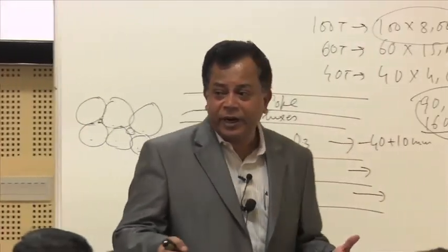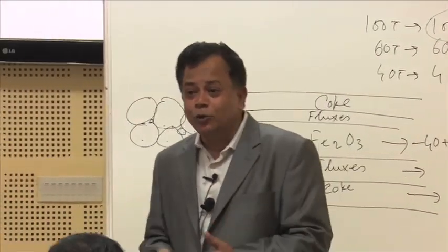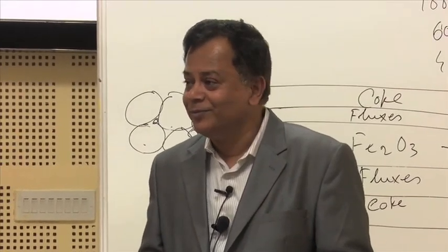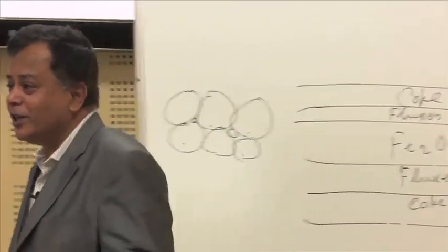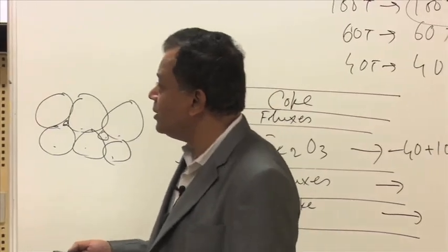Even if your mined coal gives you proper liberation, for the separation do you have equipment? Suppose I have to process coal of 1 meter size in my equipment, whether my existing equipment can handle a feed size of 1 meter, that also I have to look at. So, this is a combination of everything; you have to make a judgment on what the availabilities are and all that.